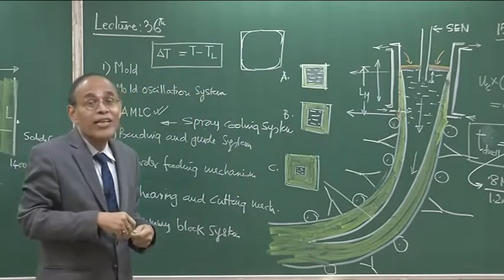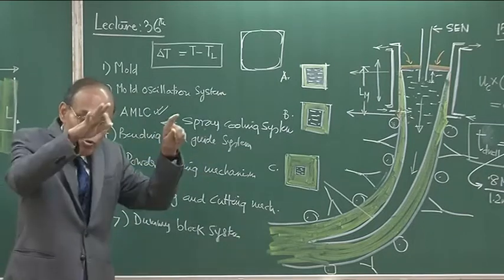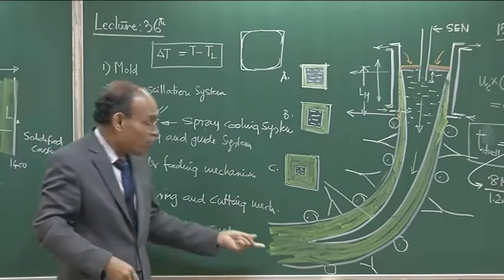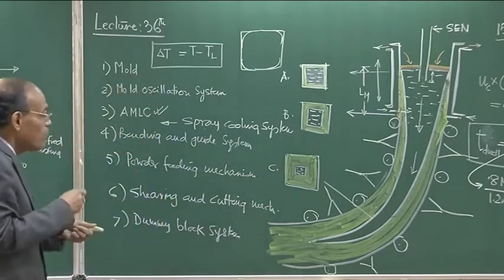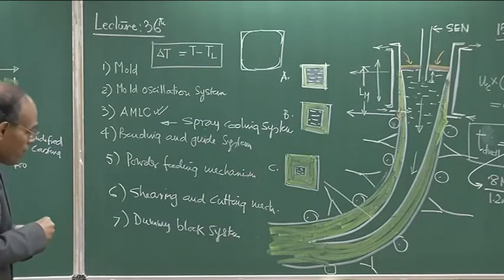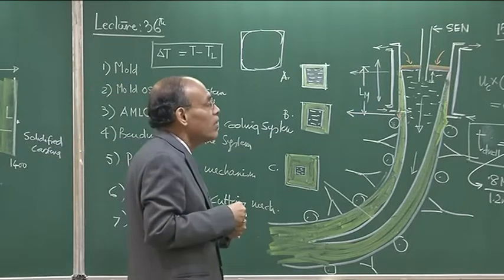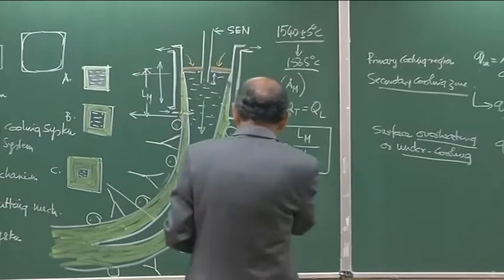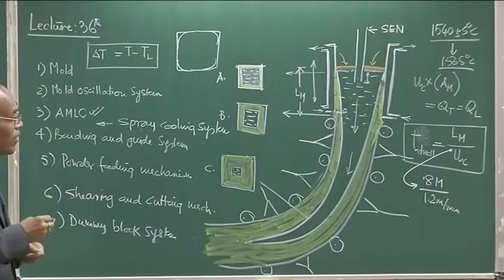You can imagine, on a daily basis in the stock yard, when these billets, slabs and blooms cool down to ambient temperature, how much heat is radiated. All kinds of efforts are now going on to tap that radiation heat, and that is an important exercise, because it is going to reduce the specific energy consumption and in turn make steelmaking more green or clean. We will talk about this aspect a little later, maybe in the concluding lectures before I wind up this course.